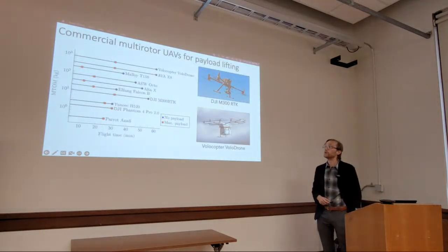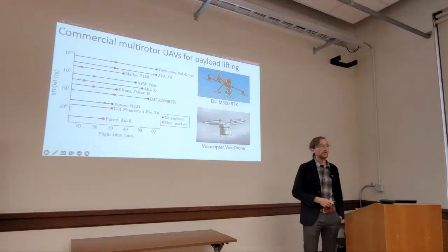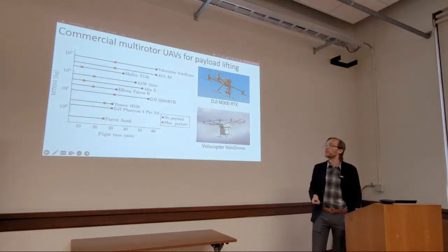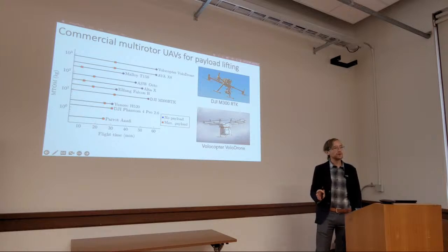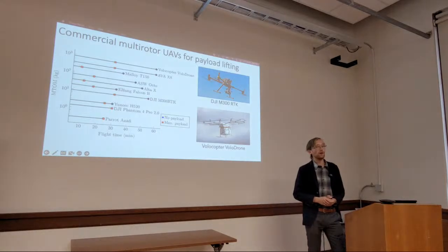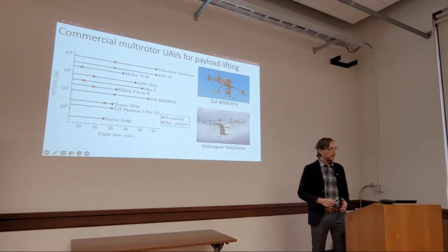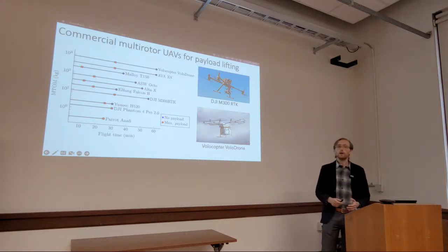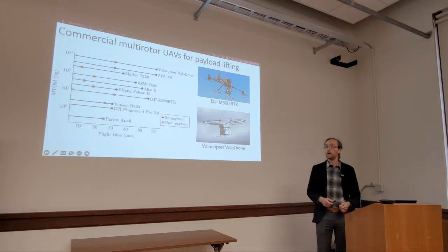And in fact, if we look at other rotorcraft that are used for diverse applications over a wide range of maximum takeoff mass, we see really that the flight time doesn't correlate that much with the maximum takeoff mass. So bigger vehicles with overall bigger disk area don't really tend to be much more endurant than smaller vehicles.